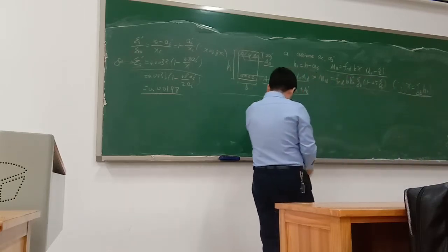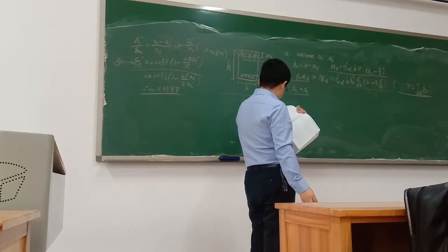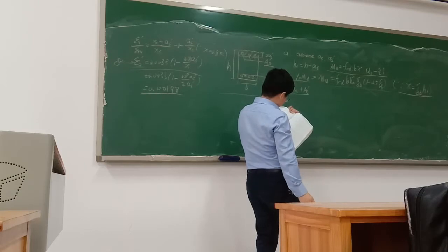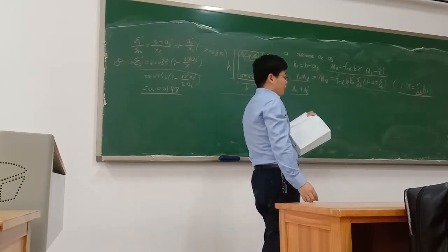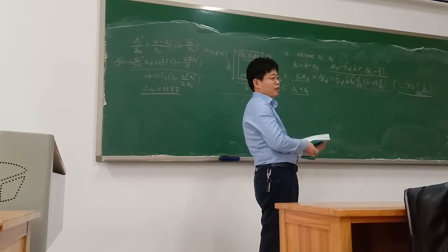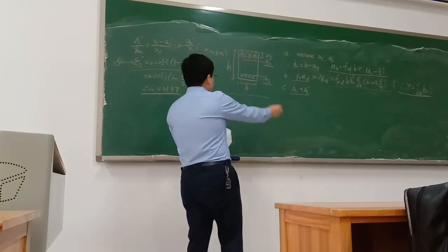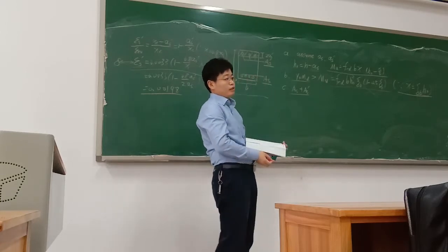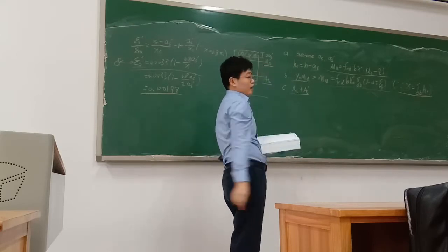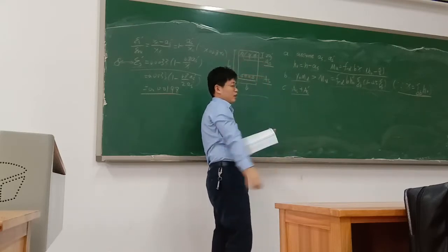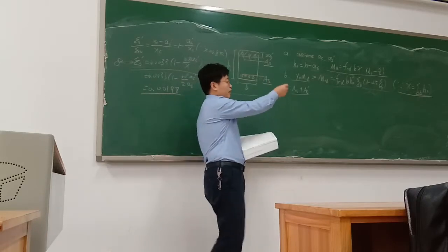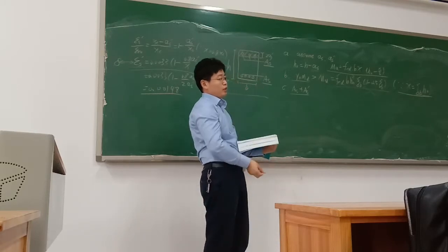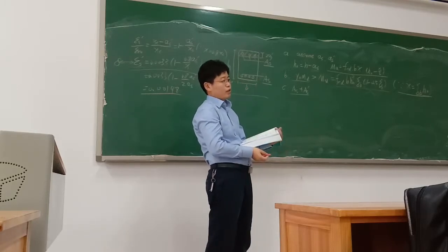So in this situation, we can use the formula in the book. There is full use of tension steel reinforcement rather than compression steel. Firstly, you have to make full use of the steel in the tension zone, and once this tension force is not enough, you use the compression reinforcement to help this section resist the load.